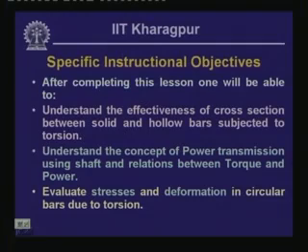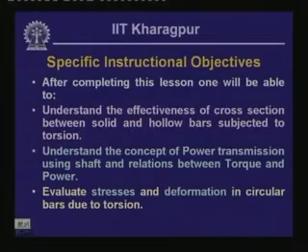Also, one should be able to understand the concept of power transmission using shaft and the relations between torque and power. This is another aspect which we will be looking into today: the shafts or bars which are used effectively in transmitting mechanical power. We will look into how this power transmission is related to the torque. Also, one should be able to evaluate stresses and deformation in circular bars when they are subjected to twisting moment or torsion.